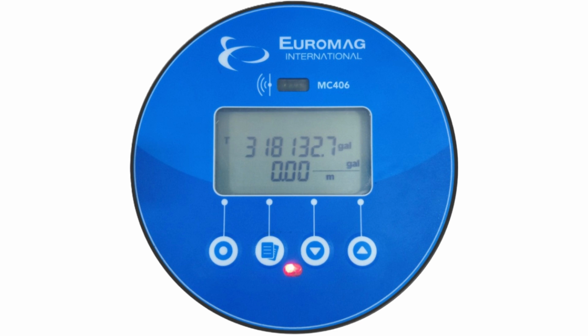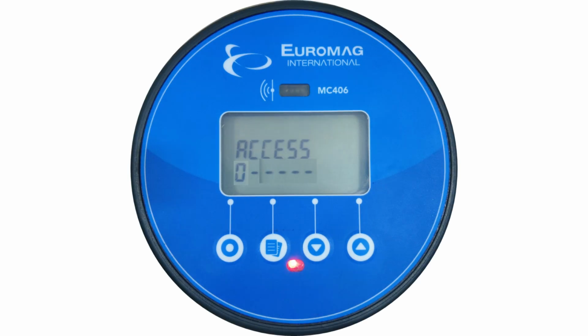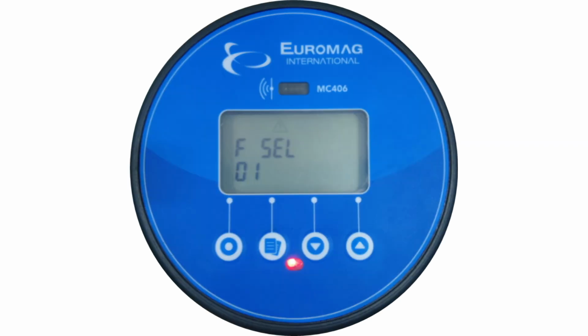The function menus allow for making changes to the configuration parameters. Press any button one time if the red light is not already on. With the red light on, now press the number 1 button one time. The screen will display access. Press the number 2 button a total of 5 times to move the 0 all the way to the right, then one more time to access the function screens.